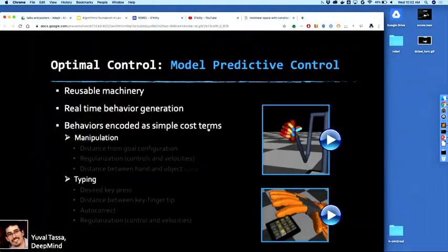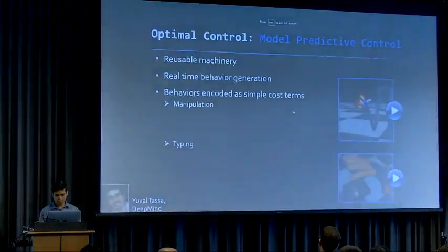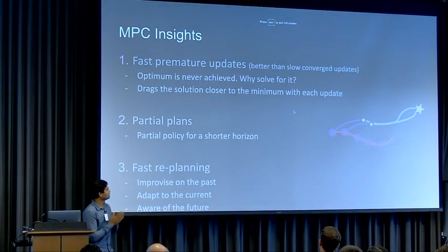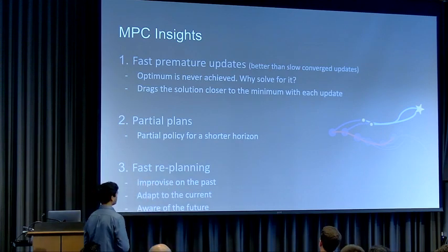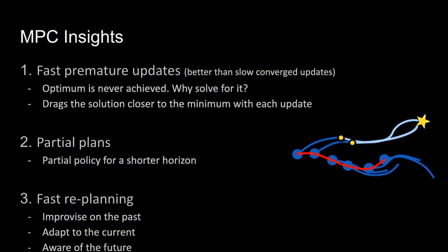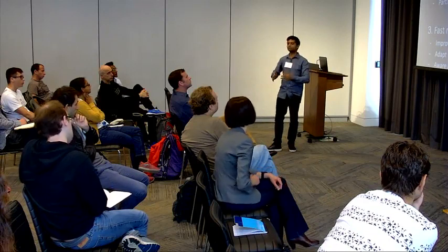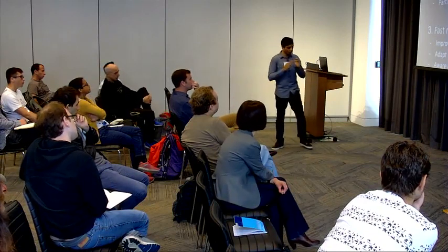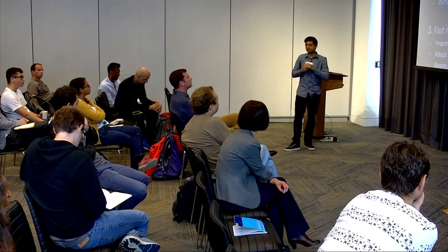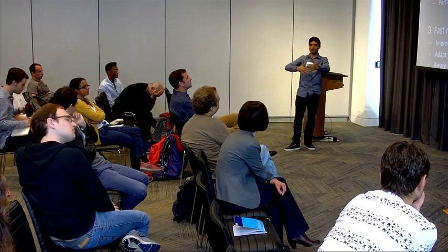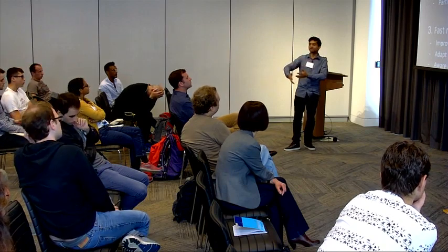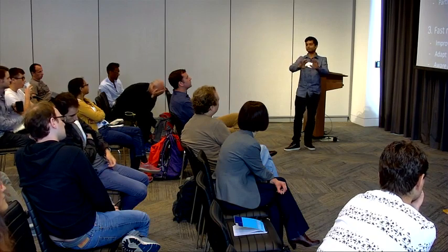All right, so I want to give my take on why I think MPC actually works and does make sense in the real world. When we are executing, we are never executing to the optimum. So even if we know how to get to the optimum in a provable way, it probably doesn't make sense to spend that compute to go to the optimum. You're only going to execute for a little bit, so your best bet is to get a good plan in this small narrow horizon. So focus your compute over there, get the best update you possibly can, and leave everything to hope.